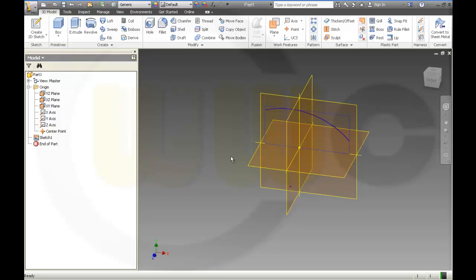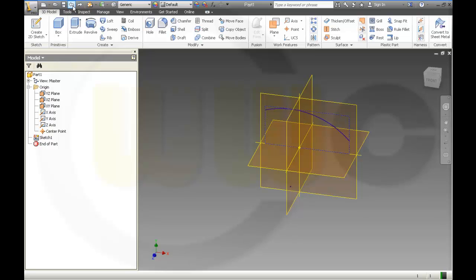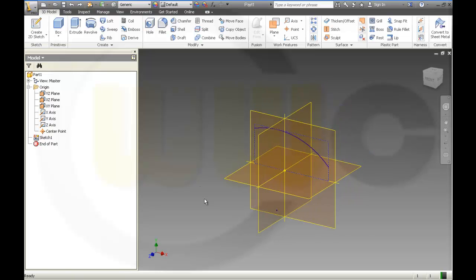If you just copy it, it may turn to a different angle. So copy it and insert it, for example, into this plane. That's the XZ plane. And you see it's mirrored 2 times. So I will redo this. Okay. Therefore I need a new user coordinate system. That's the x-axis, that's the y-axis, and if I turn this one by 90 degrees, it should work.